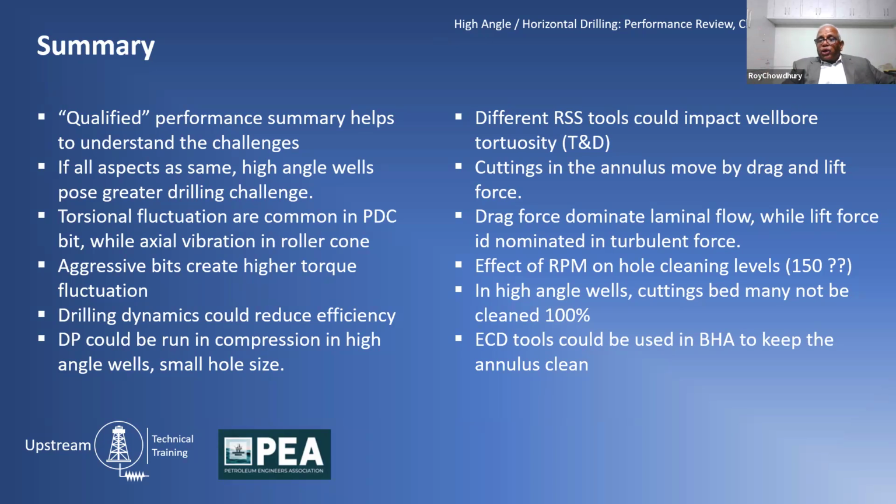A lot of people do not use a jar. For the jar to be able to trigger and have the impact, I would rather have a couple of heavyweights on top, because you need to have an impact. I will have a couple of heavyweights, and there are jar calculation models available with the jar companies. They will give you a specific recommendation, and you run these recommendations through torque and drag.